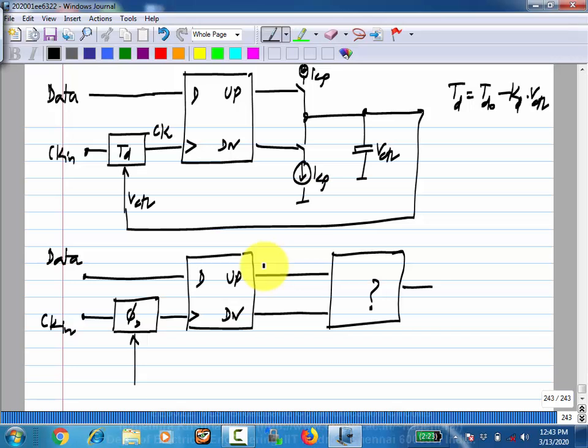It shifts the phase of the clock by some amount, and this is the controlling number, and let's say phi d is some phi d 0 minus n control times phi LSB. Phi LSB is basically, for a unit change in n control, how much the phase gets shifted.